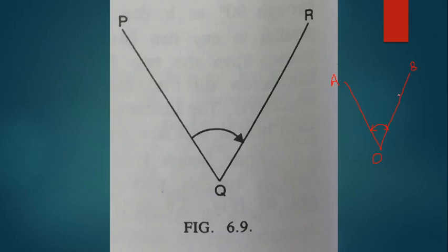Then the theodolite is set up at O and complete all temporary adjustments, that is centering, leveling, and focusing. Then vernier A0 reading should exactly match with the zero of the main scale. In order to do so, we have to release both the upper clamp as well as the lower clamp, then turn in opposite directions till vernier A0 exactly matches with the zero of the main scale.